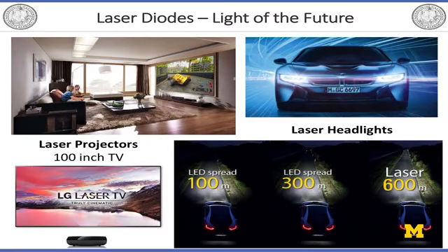And also automobile headlamp, they already use laser lighting. This blue laser diode excites phosphor to make white. And the advantage of laser lighting is the irradiation distance, which was 600 meters, now it's 1 kilometer. Up to 1 kilometer we can irradiate.